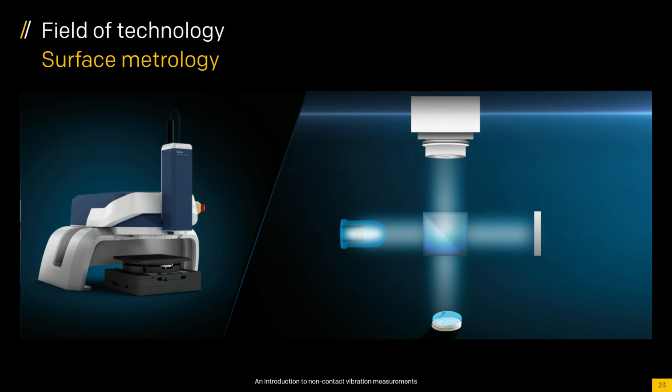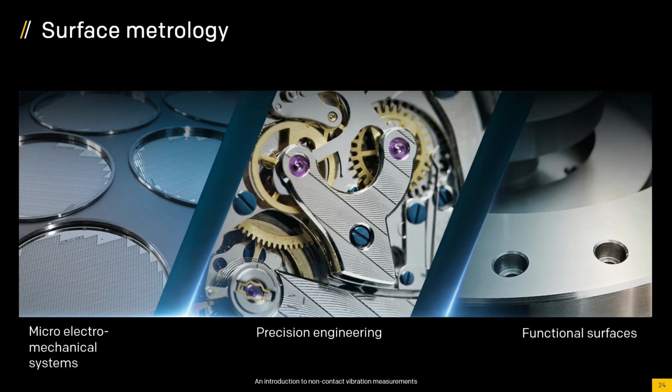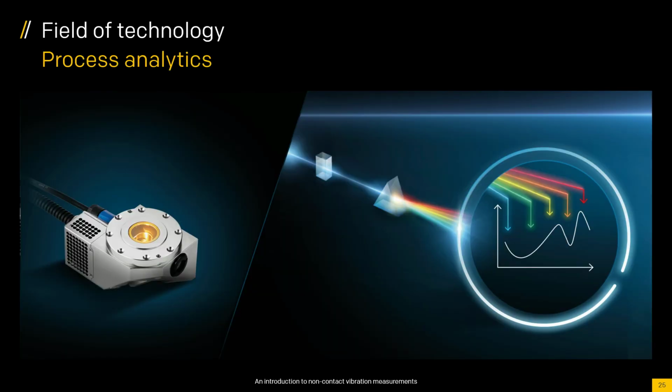Frankly, it's just about the data acquisition side of things. If you have your own data acquisition and you're doing a sweep, you would use peak hold for averaging, because that's always going to take the highest in a particular bin.